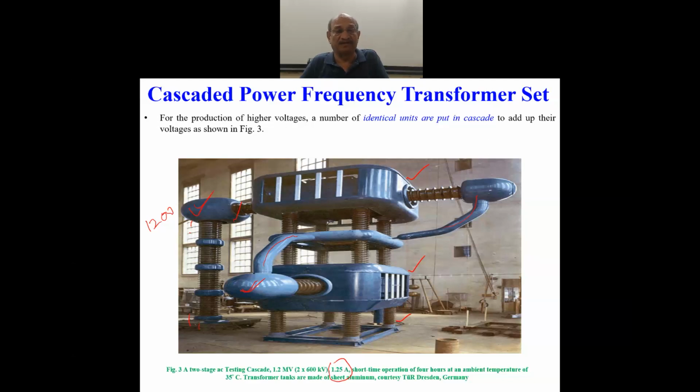You should know by this time, partial breakdown or corona activity would take place. So all these connections would have had corona activities if you had taken a thin wire instead of these thick piped conductors of large radius.